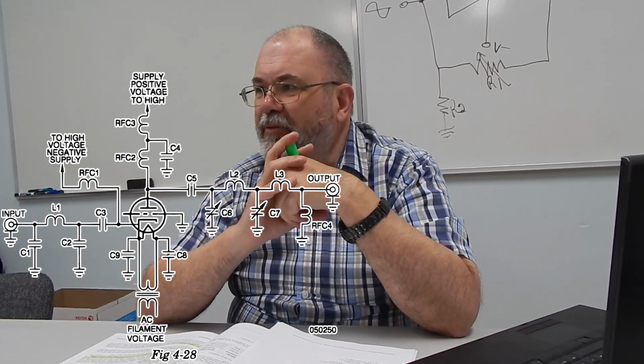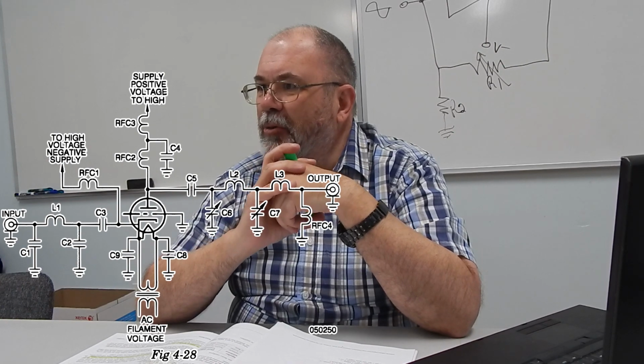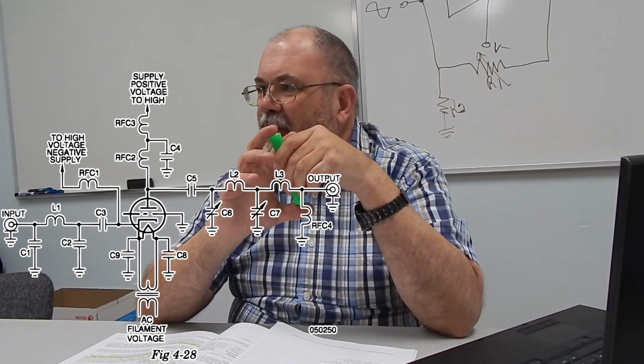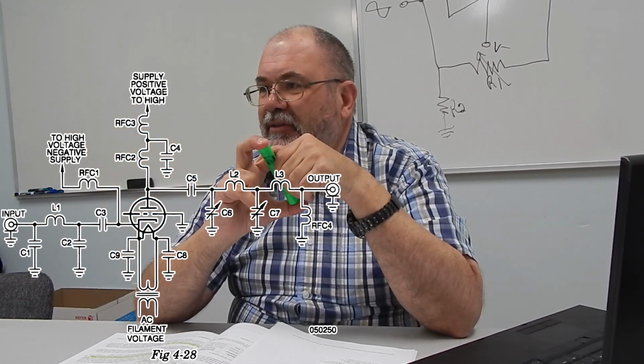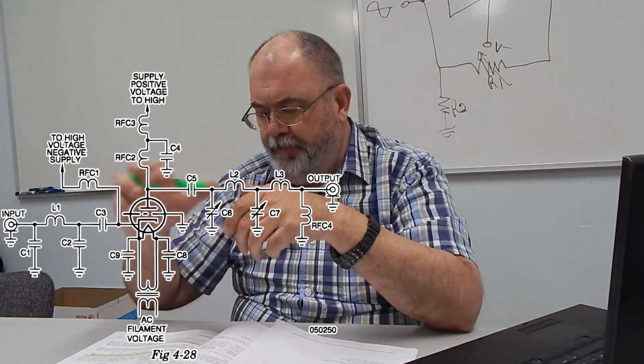So just a little bit of stuff to think about here. Got to remember that we're working in an area where we have very strong RF signals, and even a short little piece of wire will pick up stuff. So it's not like DC or even audio electronics where that much wire you don't even think about, right? Well, now we have to think about it.